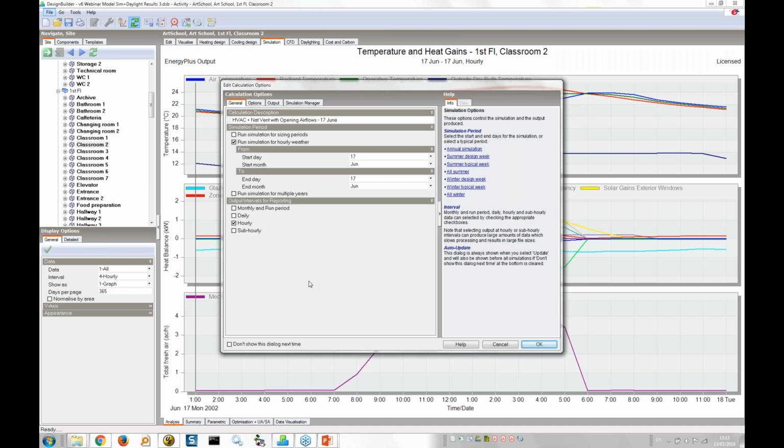A typical example is when modeling 2D ground domains, where the thermal mass of the ground itself is simulated in detail. Similarly, when simulating a ground heat exchanger, it can take several years for the ground temperature fields to stabilize to periodic steady state. Another potential application is for buildings with very heavy exposed mass concrete or stone walls, where it's important to ensure that the simulation start conditions are well represented.